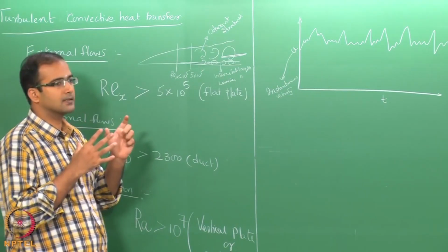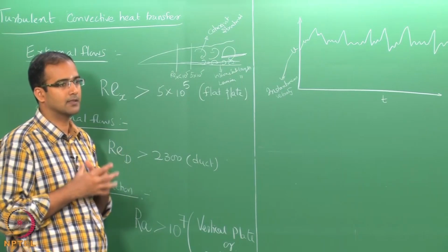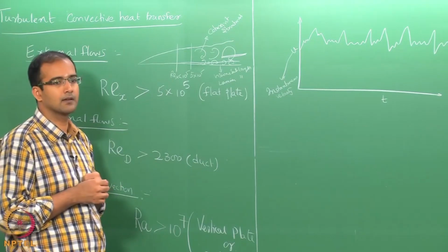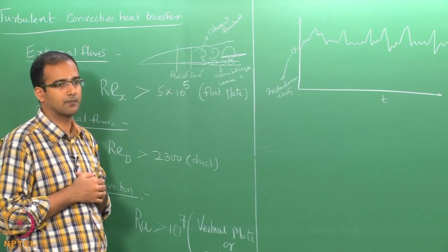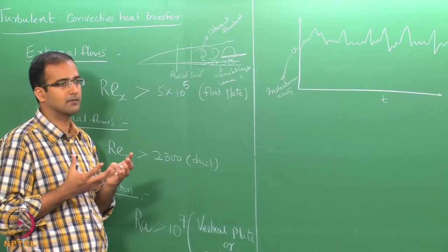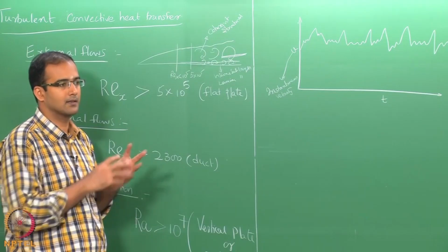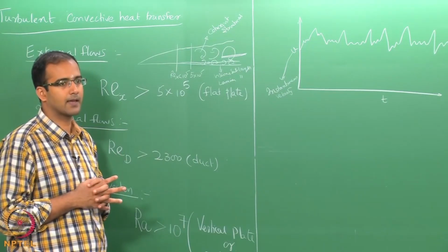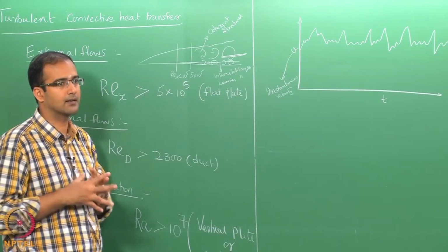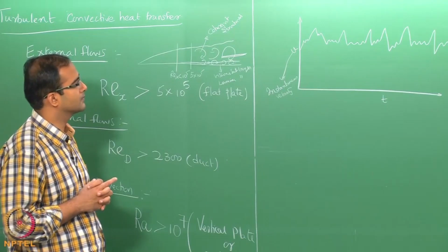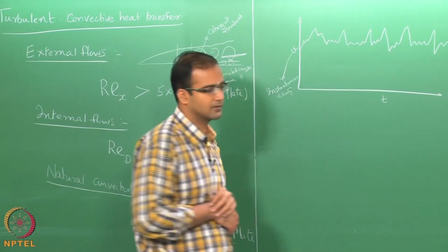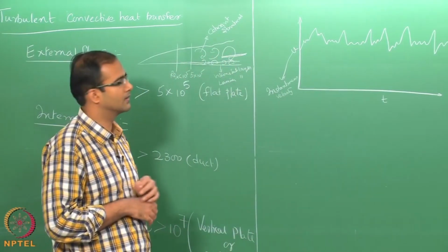Now, these fluctuations represent that there is inherent turbulence in the flow field. Okay. In a laminar case, you would not see these fluctuations; it will be a constant value at that point in time. Initially there could be some unsteadiness, but finally once it reaches a steady state condition, it will not change. But in the turbulent case there is nothing like a true steady state; there will always be an inherent fluctuation that you will observe, and therefore this represents the nature of the turbulent flow regime.